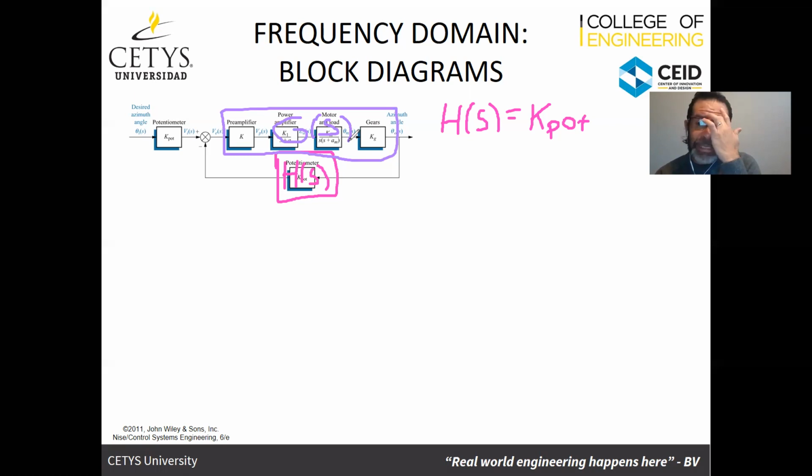In block diagrams, the algebra of block diagrams is that if I have boxes that are next to each other, so there's one box that feeds into another box that are connected in series, boxes that are connected in series literally multiply each other. So these four boxes that I have here, to obtain the whole box that represents G of S, the only thing I need to do is to multiply these four transfer functions.